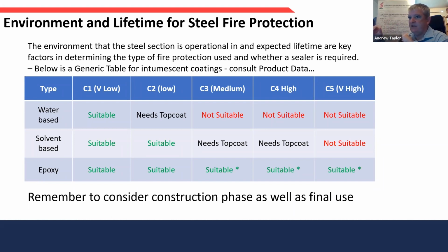And what you will see is that different products, and this is a generic sort of thing. I say that, so you must consult product data, because some water-based it's possible to make them more durable. It's possible to make solvent-based more durable or less durable than is implied here. But what tends to happen is that a water-based will provide less durability in harsher environments than a solvent-based, and the epoxy systems will provide most durability. And there are some new novel systems that sit somewhere between solvent-based and epoxy coming to the market.